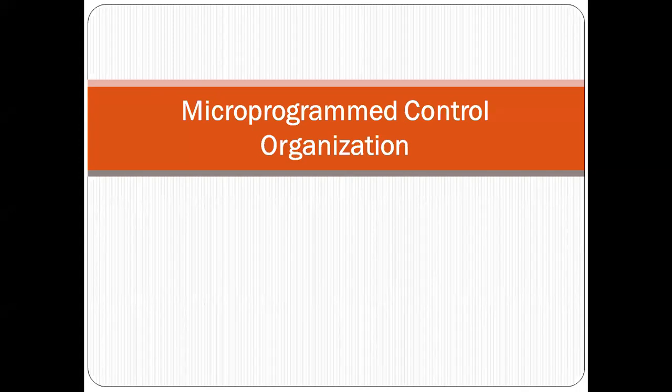They select one of the registers in a common bus system. We have seen there is a mux that will select one of the registers which places the data onto the common bus, and activate either the load control, increment control, or clear control. Okay. And other controls will select one of the ALU operations. So these are all different control signals needed at a particular time instant so that your complete instruction execution procedure will be fulfilled.